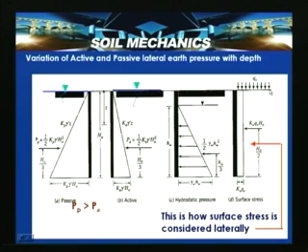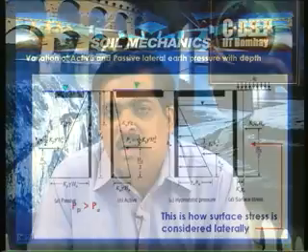If you have different, more complicated lateral stresses, they need to be considered in the subsequent design. Basically, this slide shows the variation of the active and passive lateral pressures, and by knowing this we can obtain the equation of this particular line and then the earth pressure diagrams. Once you obtain the pressure diagrams, you can calculate the active thrust and passive thrust, and by considering the equilibrium conditions we can design the wall for equilibrium.